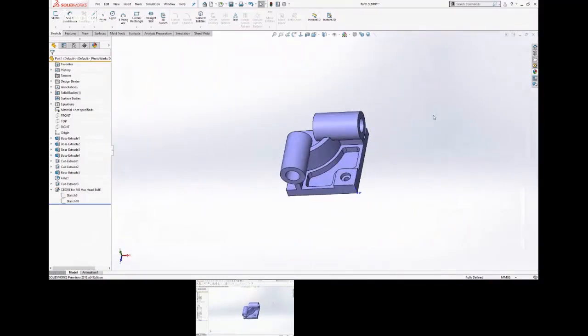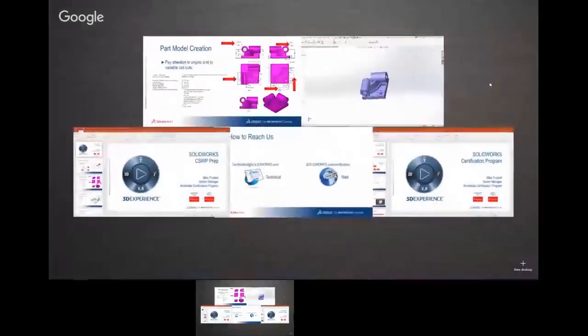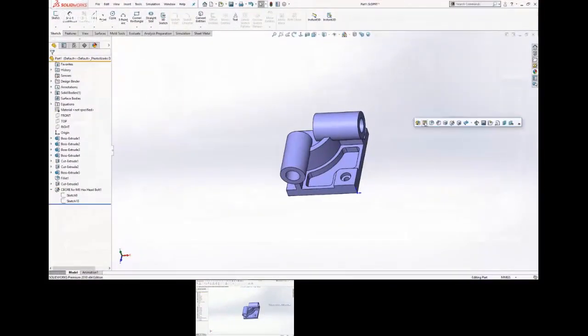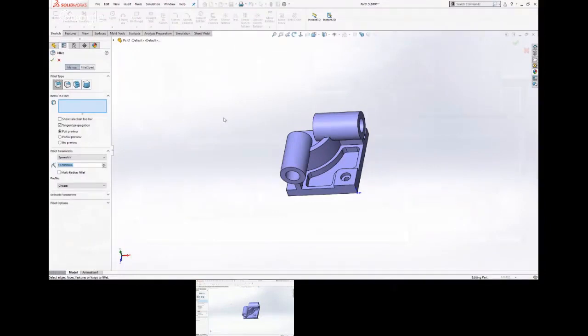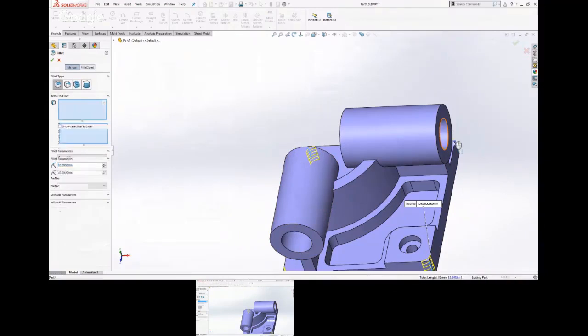All right, two more things: the fillets on the corners and the chamfers. The fillets are called out as 10 millimeters. So we'll grab the fillet tool, it's set to 10, and we'll grab these edges. Again, I can select through, as long as I don't have my mouse on here, the 3D mouse, I can select that edge because it hasn't turned it off.